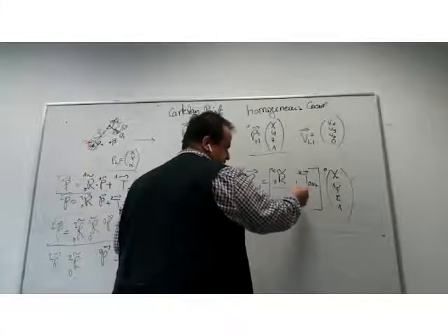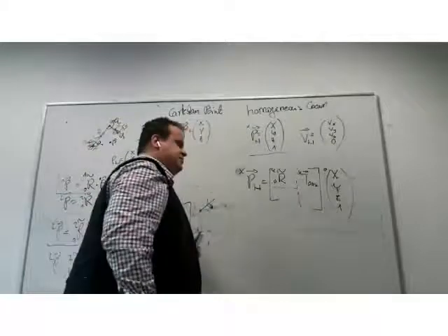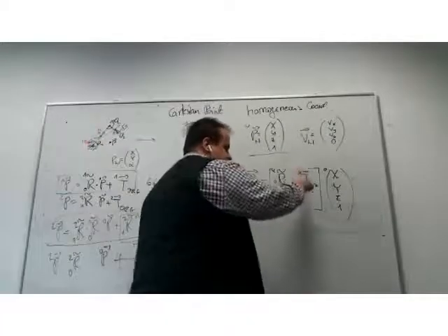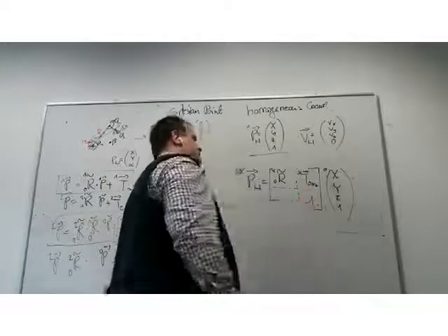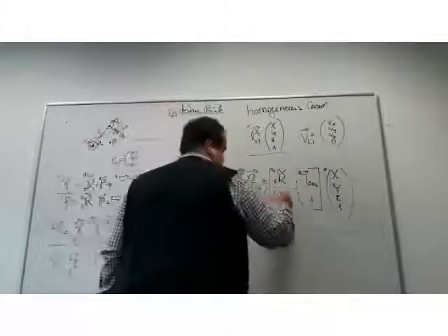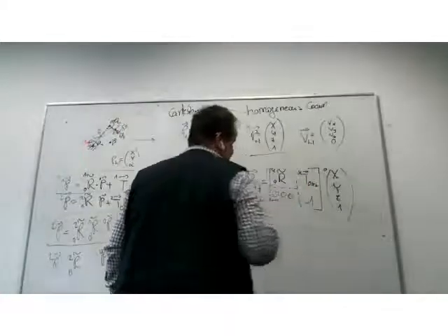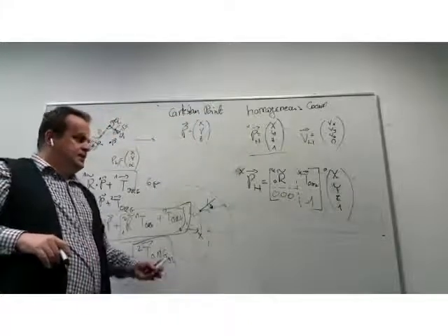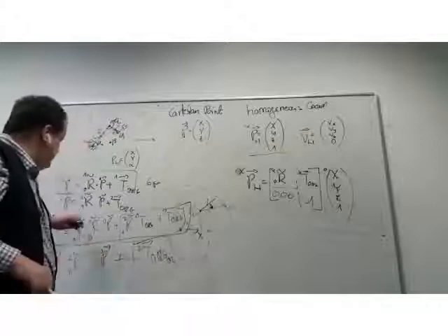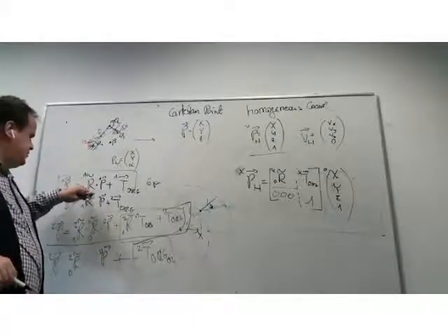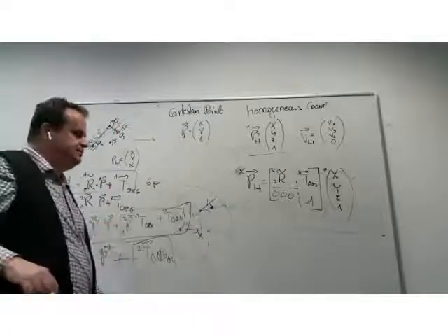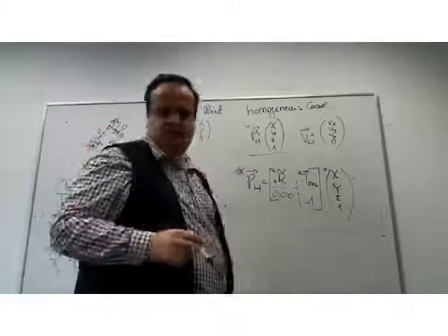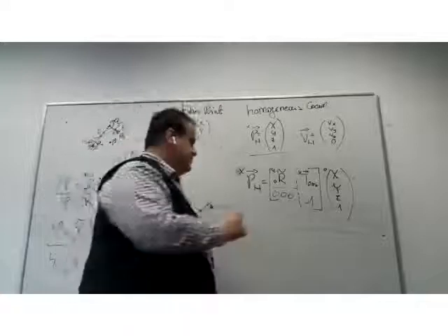Actually, if I give you the origin, the P origin is already in homogeneous coordinates. This will be x, y, z plus 1. And it's still 0, 0, 1 here. So instead of writing my coordinate transformation as rotation times point plus translation, I combine it all in one bigger transformation matrix.